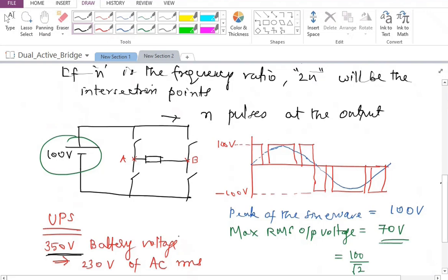In many household applications, we may use only a 24 volt or 48 volt battery. So what we get at the output of the inverter will be much less than that. We may get only 35 or 30 volts, and that has to be stepped up to 230 volts before it is utilized by our home inverter. That is the reason why we should know exactly what voltage rating and ampere hour rating of the battery we need to choose for a particular application. That's important.